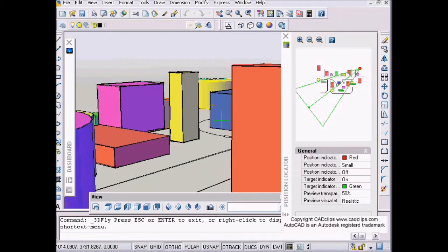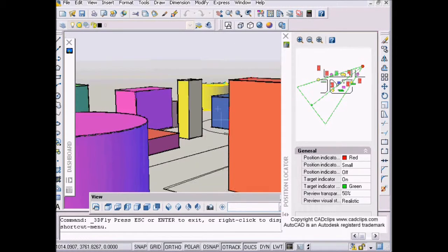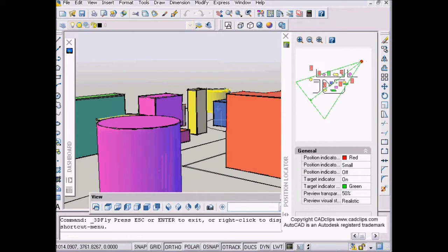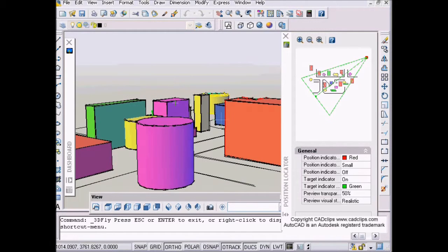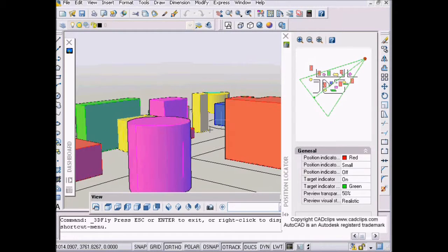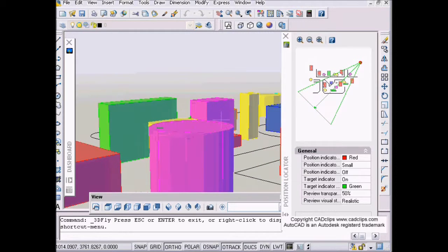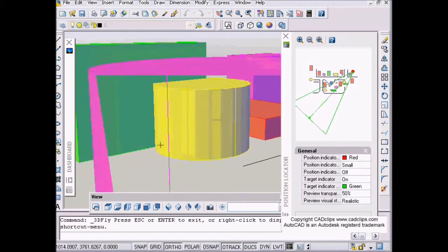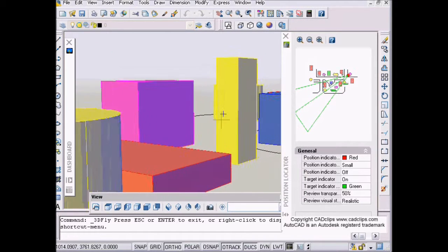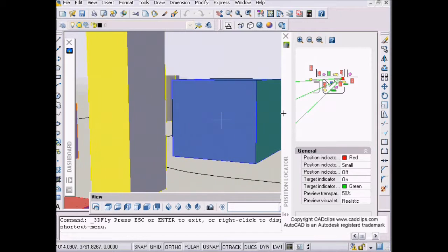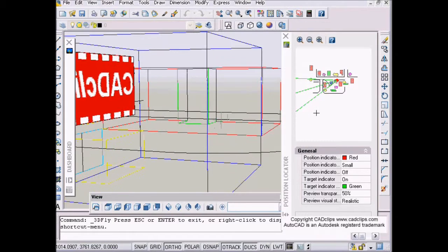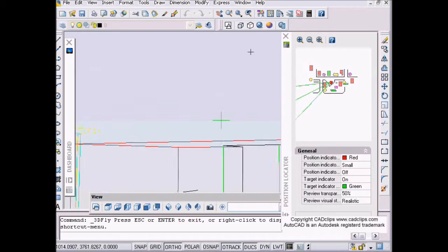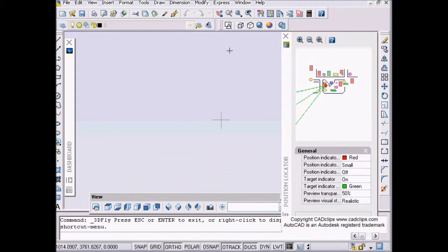So if you want to go up higher, you can wheel in. So I'm just wheeling right now, and you can see what's going on over here. Wheeling out, basically turning around and resetting for my fly through. Okay, so here we go again. I'm going to use my arrow key, and I'm going to hold it in, and then now I can fly by. Maybe go down, try to work my way around here. Notice what happens when you get too close. It just kind of goes through and there's a transparency effect. Okay, flying up, and then you can start to move your mouse above and you'll start to go up higher, etc., etc.